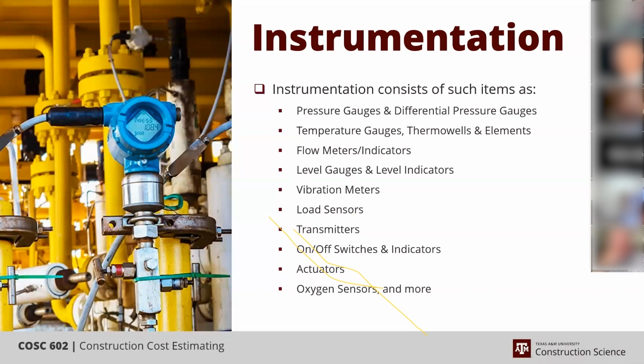Well, thermal wells allow you to change out instrumentation without shutting down the equipment, because you wouldn't be protected from the process. If you had to change that instrument, you'd have to shut it down, clear it. So the thermal well gets you around that.